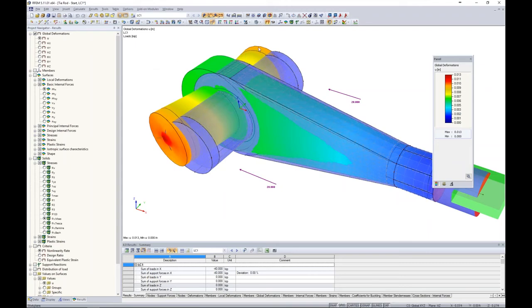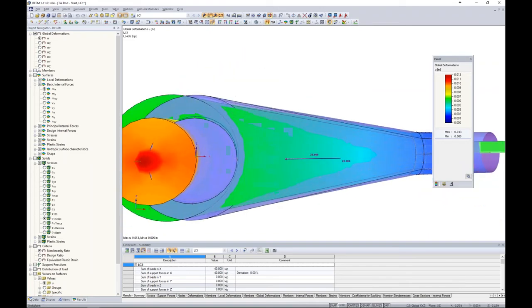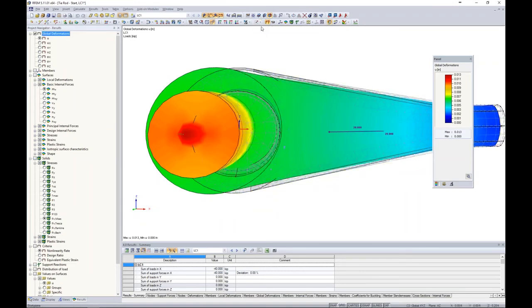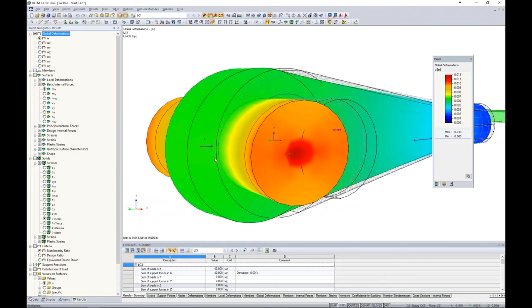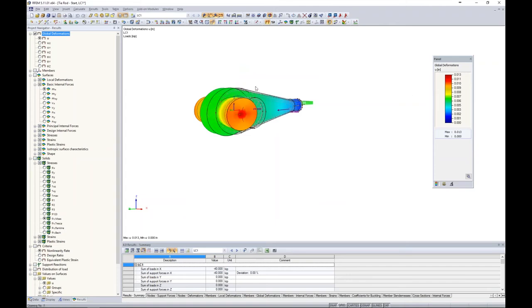So with this bolt element passing through the eye, and we turn this into elevation view and maybe into wireframe, we can see here that it looks like the bolt is fully fused to the front portion of this ring element. This is not really what's going to happen. In reality, what we would hope to happen is that this bolt would release away from the ring element where we have tension forces, but in the back, we would still have full fixity here where we have compression where the bolt's bearing onto the ring.